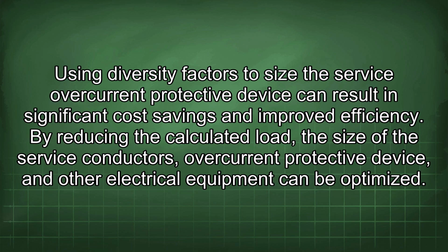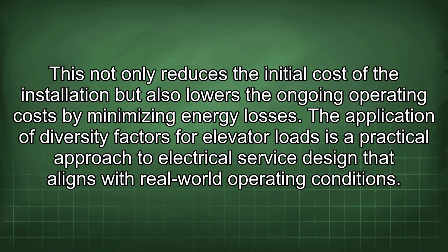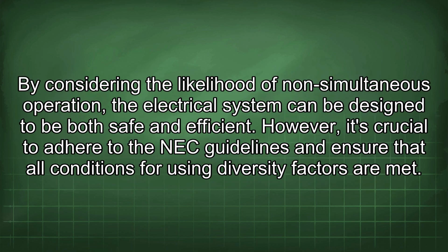By reducing the calculated load, the size of the service conductors, overcurrent protective device, and other electrical equipment can be optimized. This not only reduces the initial cost of the installation, but also lowers the ongoing operating costs by minimizing energy losses. The application of diversity factors for elevator loads is a practical approach to electrical service design that aligns with real-world operating conditions. By considering the likelihood of non-simultaneous operation, the electrical system can be designed to be both safe and efficient.